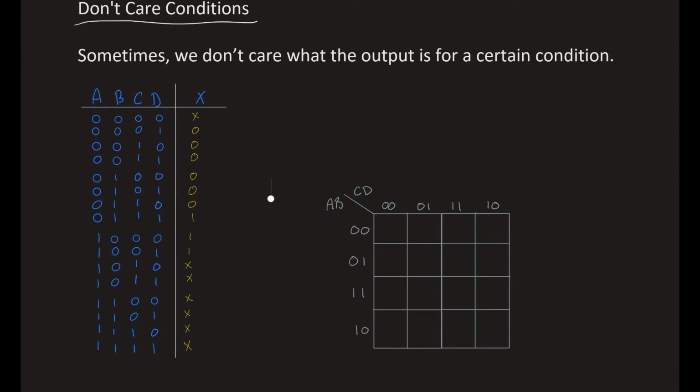For lots of designs, I can't really give you a good example now. I can kind of try to give you an example. We're gonna see a lot of them later on. There are certain outputs we literally just don't care about. Like, later in the semester, we're going to work with something called a 7-segment display. It looks like this. If we were in the lab, I'd show you all the equipment has them on there. Or if you look at older displays, if you want to put the number 2 out, you just turn this one on, like that, and you get the number 2. Well, in those displays, values over 9, so 10 through 15, they just can't happen. They just don't happen.